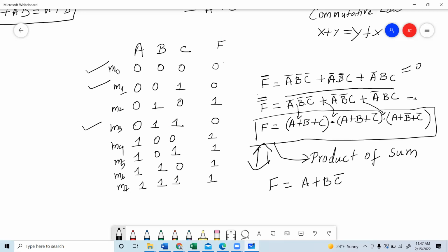So the XOR gate says that A bar B plus A B bar is equal to A XOR B. We will see what XOR is. It is an odd detector, meaning it detects an odd number of ones in the circuit. If there is an odd number of ones in the input, then it is going to produce 1. If it is an even number of ones, it is going to produce 0. So that is the XOR. We'll talk about this, which is very, very important for building our adder circuit. We'll talk about XOR, but before that,